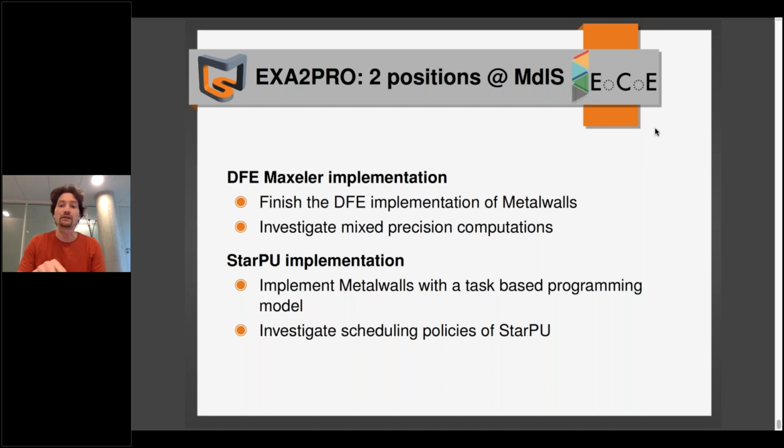But there is a need to know which precision your algorithm requires, and it is not clear how you do that. But definitely that's where FPGA computing could win even more compared to CPUs. The factor of 3 to 5 that I'm talking about, with the performance model, is in double precision. So using the expensive double precision implementation on FPGA, we still get an acceleration of 3 to 5 compared to CPU.